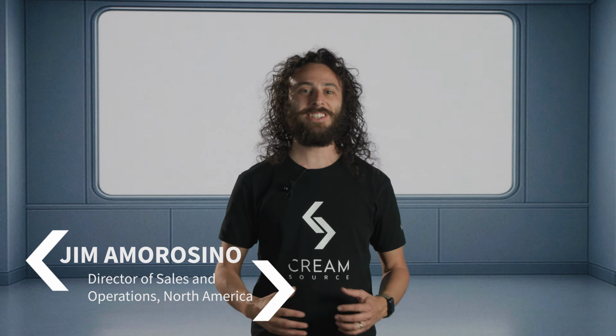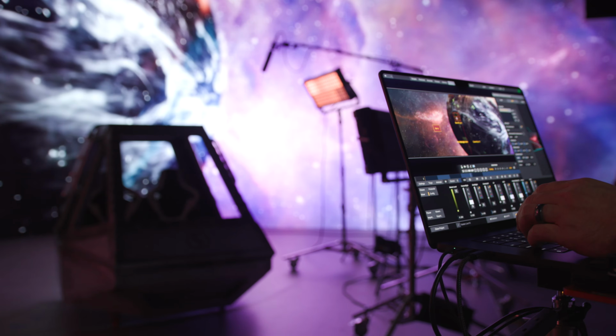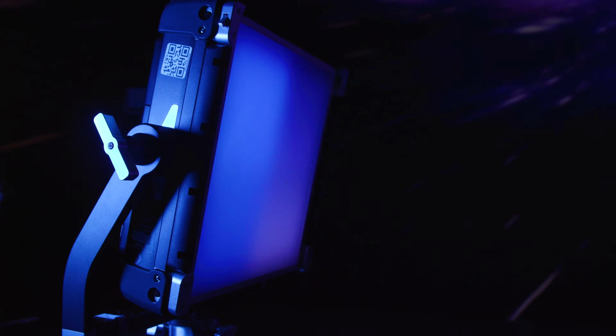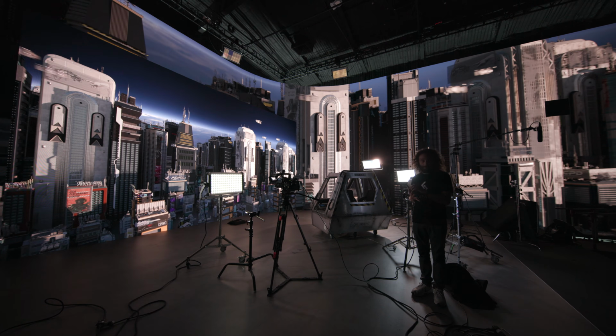As lighting and technology continue to mix and merge, we're seeing a rise in a new style of lighting: image-based lighting. Image-based lighting samples a video or virtual environment and communicates the color and motion, typically in the form of RGB or XY coordinates, to the lighting fixtures, allowing for real-time, immersive lighting. This approach is great for creating ambient environmental lighting when shooting on a volume, or if you're just looking for a more nuanced lighting effect while shooting on location.